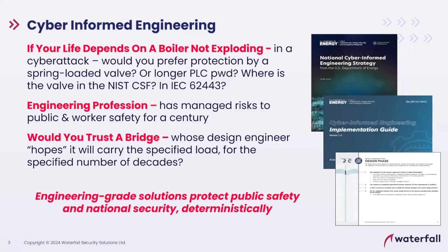Would we prefer a mechanical valve, where a piece of steel is forced against a spring? If the steam pressure is too great, it forces the steel against the spring, the steam escapes, and there's no explosion. Would we prefer a mechanical valve, or a longer password on the PLC controlling the furnace? Most of us would prefer the electromechanical valve.